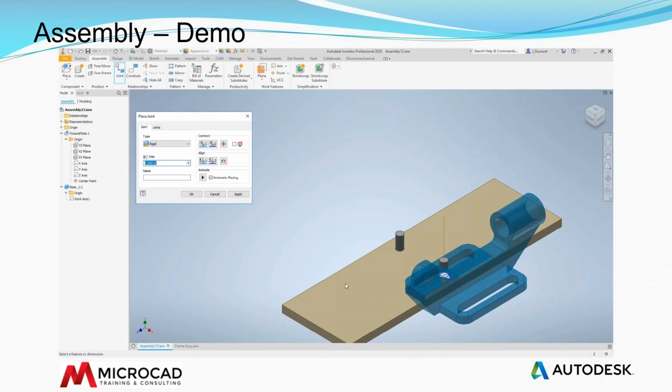You'll see a brief animation showing me that that particular joint will be rigid. That's a type of joint, and there are several that we can choose from. By default, this one is going to be rigid, and that's going to remove all the degrees of freedom, and this component will be fully constrained. In this particular case, because it's a slot, I would actually like the part to slide. So I'm going to change the type of the joint to slider.